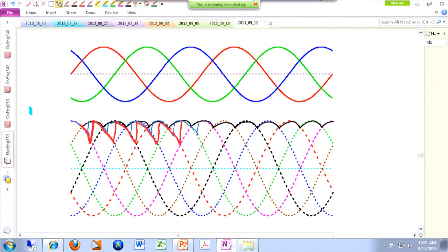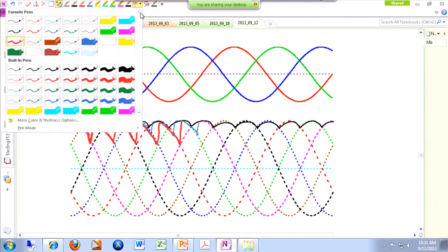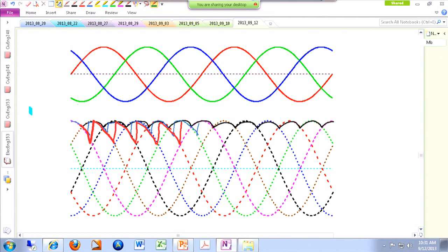Or if you're going to make it even further, you can create something like, let me get a better color, green. So as you can see, it gives you an extra degree of freedom to control the DC value of your output voltage, basically. So this is a controlled rectifier.